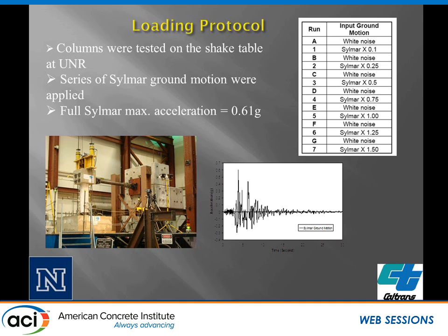So as the table moves back and forth, this mass moves back and forth. Again, that's the inertia mass that would come from the bridge. The problem with moving it off is now it doesn't provide you with the axial load that you need in your system, and so we have vertical rams here that provide that axial load.